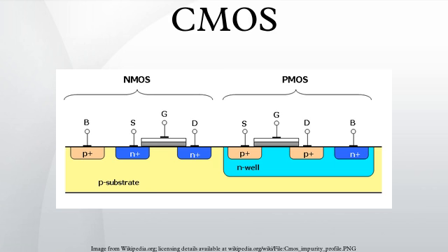Since one transistor of the pair is always off, the series combination draws significant power only momentarily during switching between on and off states. Consequently, CMOS devices do not produce as much waste heat as other forms of logic, for example transistor logic or NMOS logic, which normally have some standing current even when not changing state. CMOS also allows a high density of logic functions on a chip. It was primarily for this reason that CMOS became the most used technology to be implemented in VLSI chips.